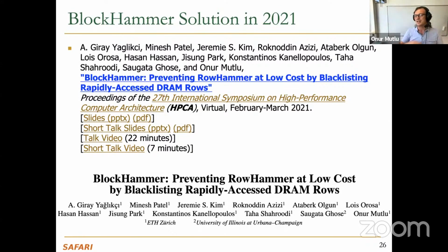Refresh basically means you read your memory periodically more often, just to refresh the memory. We're going to talk about refresh in one of the lectures soon also, so you will get an idea about it. So you don't want to increase the refresh rates to solve a problem like this, but people do it, and it's not clear how secure it is, because our original paper showed that to make DRAM fully secure based on what we have tested, you really need to increase your refresh rates by 7x.